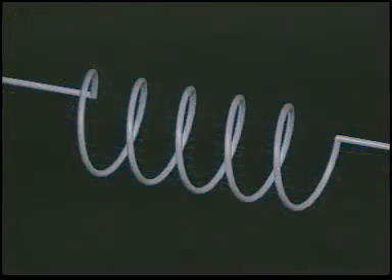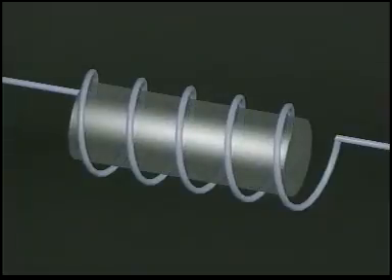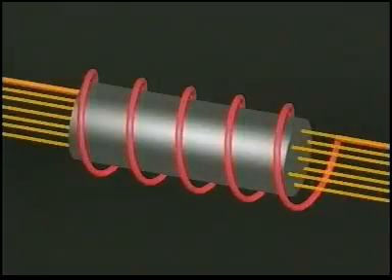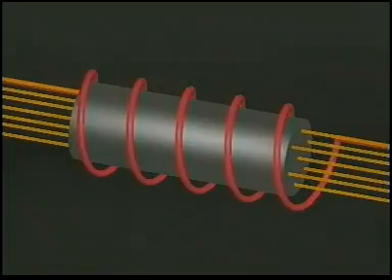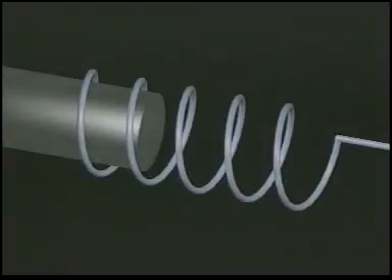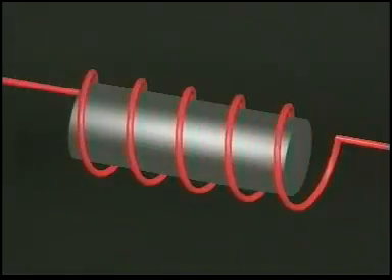If a soft iron core is inserted into this air core coil, the electromagnetic force is amplified considerably. This is the principle on which solenoids are based. Another phenomenon. If the soft iron core is movable, it is drawn into the middle of the coil when current is applied, thus producing a magnetic field. In this way, the core has the function of an armature.